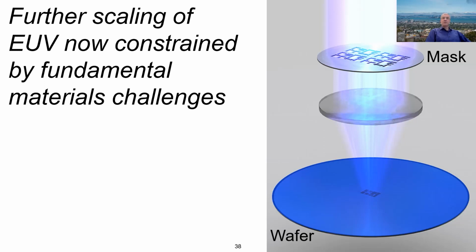So today with EUV, we print things that are about 22 nanometers in spacing, where we need to get to enable the next decade and a half of technology is to go to something like 6 nanometer lines and spaces, or 12 nanometer separation of the lines.